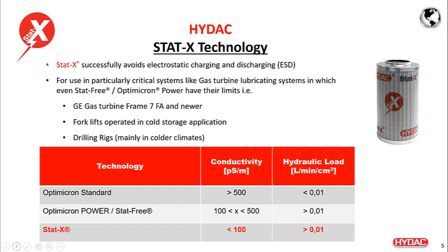So the conductivity goes down when the temperature goes down, and then lower temperature operation of the forklifts caused a lot of issues with the electrostatic discharging, especially with the plastic tanks. And also the drilling rigs when mainly operated in the colder climate. So having those applications and challenges in front of us, HYDAC developed the media that was sophisticatedly working in these applications and helped us work at much lower temperature and much lower conductivity at much higher hydraulic load. So how are Stat-Free and StatX separated, and how do they work?